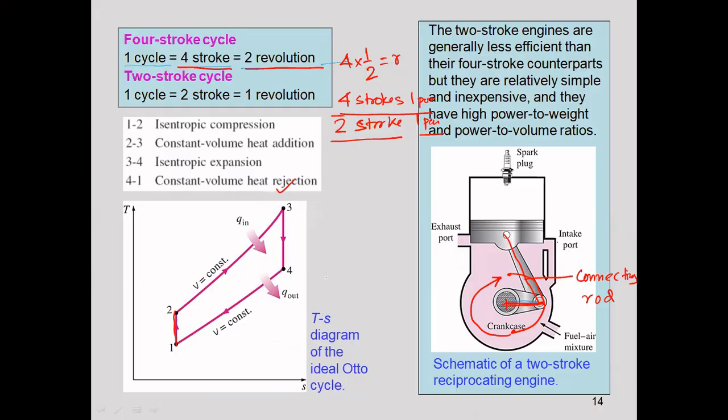Now for constant volume, you have studied in thermodynamics 1, that is basic thermodynamics, what is the slope of this line? Slope of this line mathematically is del T by del S, because it is a TS plane. So slope will be del Y by del X. Here Y means temperature and X means entropy. So del T by del S at constant volume.